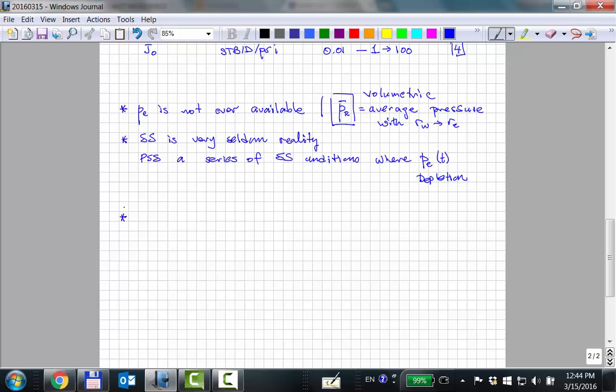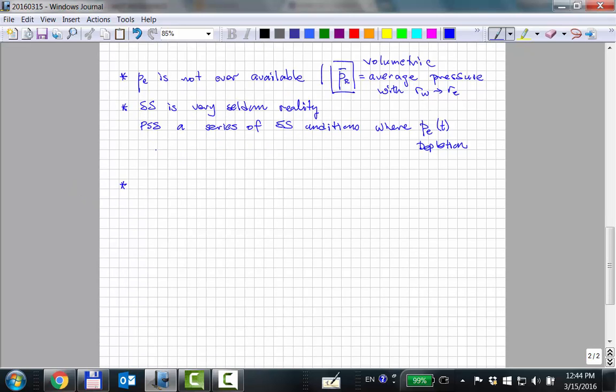Another thing that's not handled in this equation that we're going to introduce here is that sometimes, because of the drillers, which is the majority of you guys, we often damage the well. When you're drilling, you've got mud in the hole, right? And the mud is to prevent it from blowing out. So we don't want that. But that mud contains particles, okay?